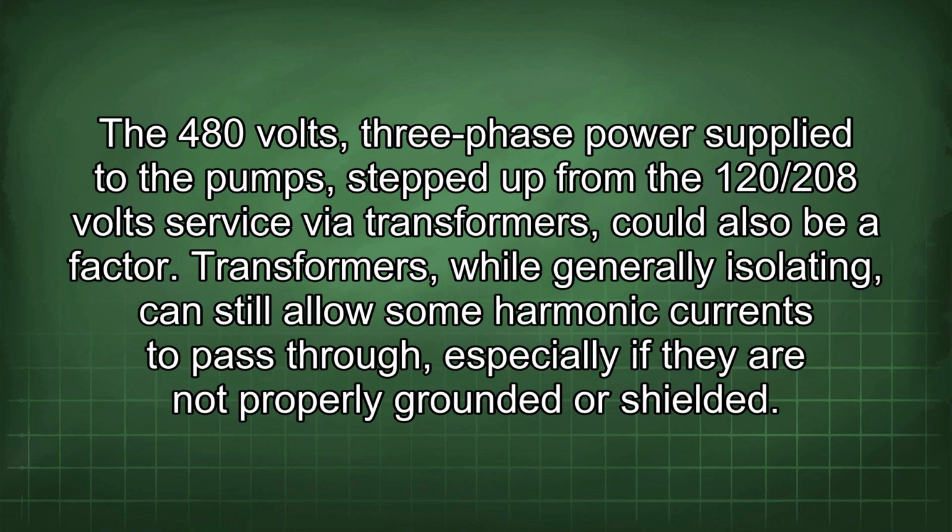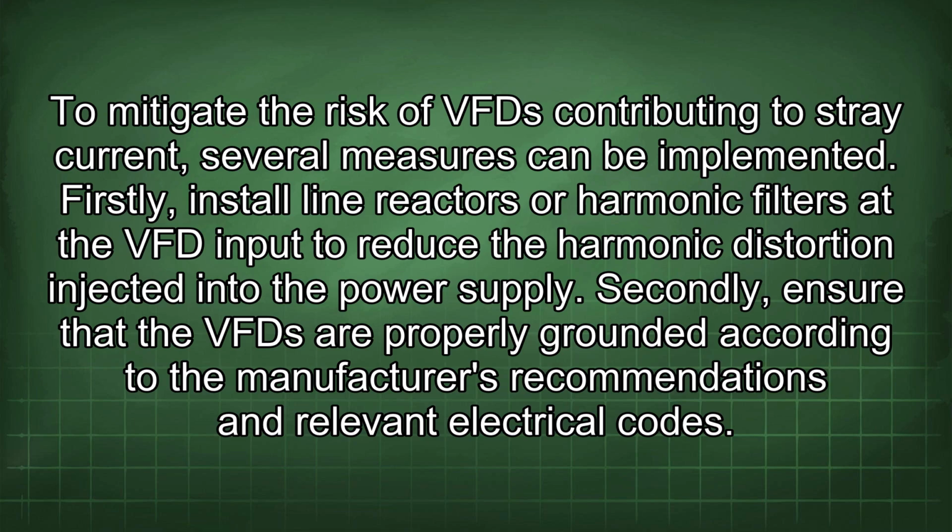The 480 volts, three-phase power supplied to the pump, stepped up from the 120/208 volts service via transformers, could also be a factor. Transformers, while generally isolating, can still allow some harmonic currents to pass through, especially if they are not properly grounded or shielded. To mitigate the risk of VFDs contributing to stray current, several measures can be implemented.